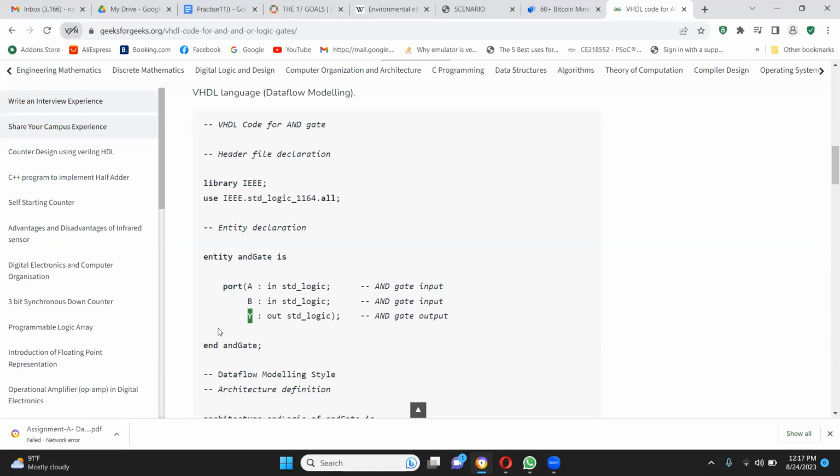You talk about synchronous and asynchronous reset. So this is a different ballgame, you know. I'm just talking about the basics. No, it is not that we will not have a reset signal for a synchronous circuit. There is also a possibility that we may have to include a reset pin or reset signal for a synchronous flip-flop also. In some cases, you might need that for your application. There is no fixed rule that only in asynchronous circuits you will have a reset, nothing like that actually.